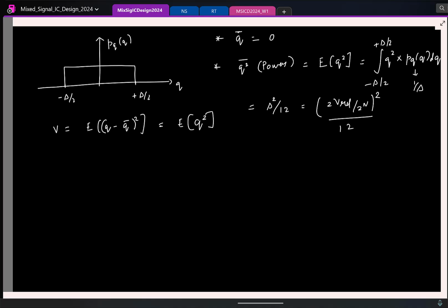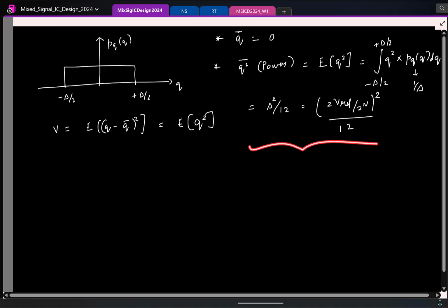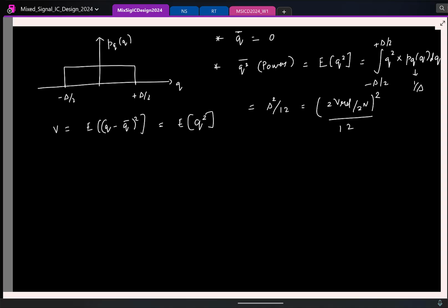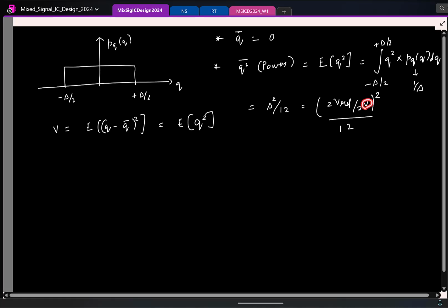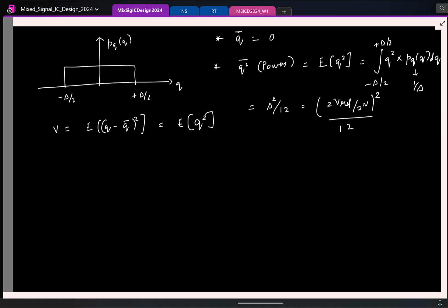Cool. So now we have gotten some information on quantization noise. So now we can try to see how we can basically characterize an ADC, right? And this seems to be a reasonable thing to do. A good ADC, as you know, should have the capacity to resolve with more and more bits, which means I should have more and more n. So which means this term should be smaller or larger? Should be smaller. It's the quantization error power. The lower that is, you can say the better is my quantizer or the better is my ADC.